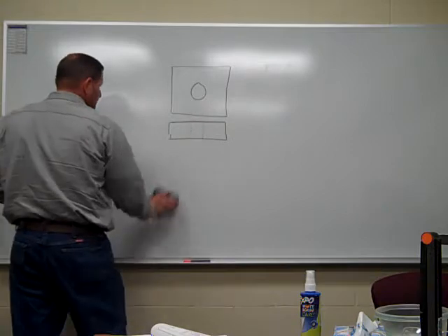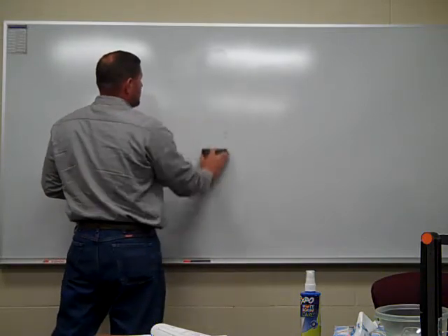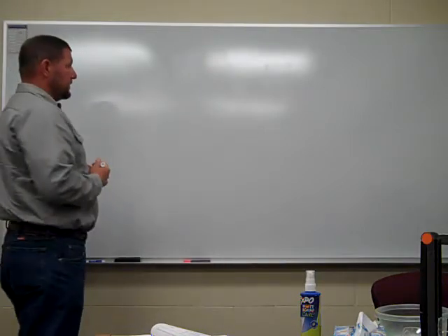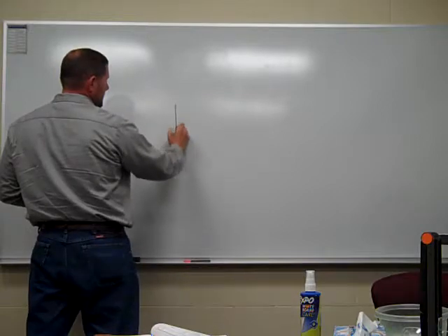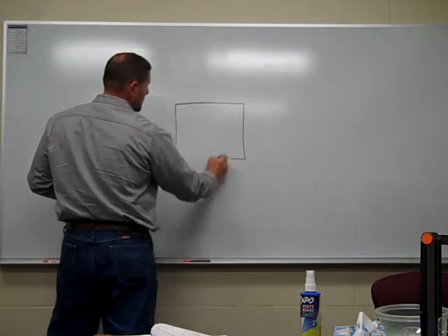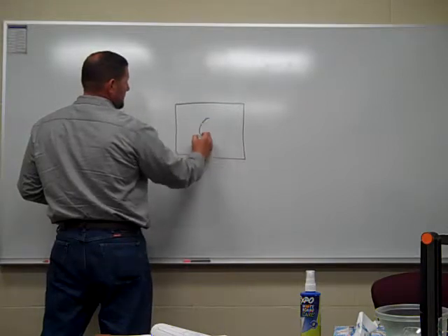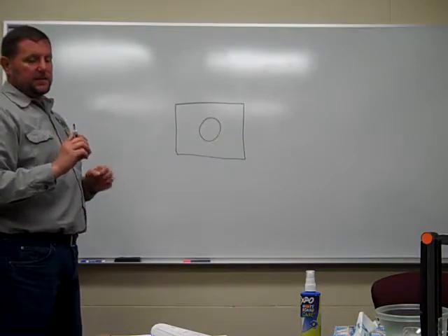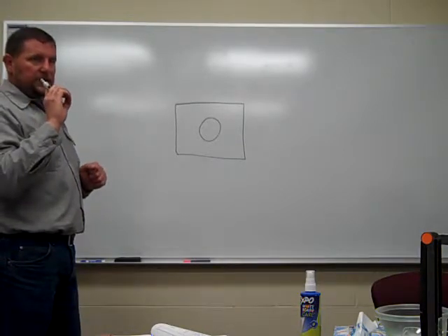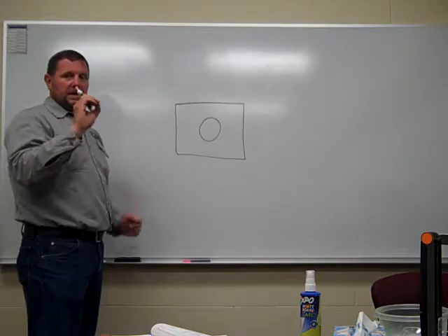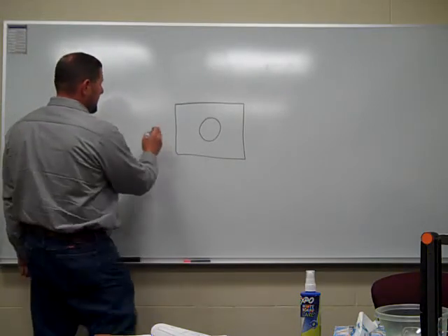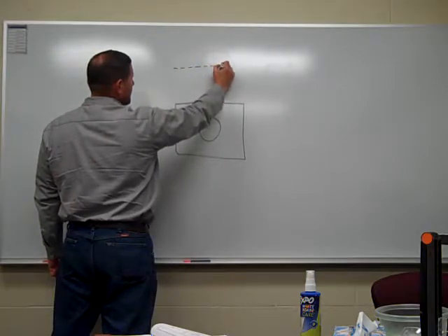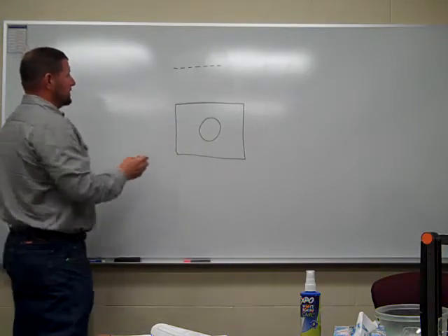Center lines. Center lines are used to depict the centers of arcs and circles. So for example, same plate, I drill a hole in here, and pay attention to these dashes on center lines, hidden lines, phantom lines, because a lot of times the only way you can really determine what line it is is the way that it's segmented. As you notice, on the hidden line all the segments are the same length. The break between the hidden line dashes is the same. Well, the center line is a little different.